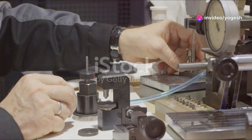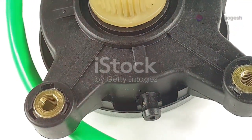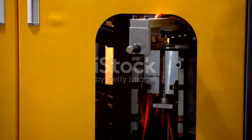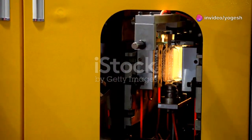Let's talk about a crucial detail in plastic design, the draft angle. It's a slight taper, just a degree or two, added to the sides of a part. Instead of perfectly vertical walls, we tilt them out ever so slightly. Why? It's all about injection molding.